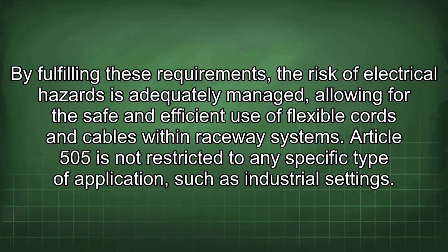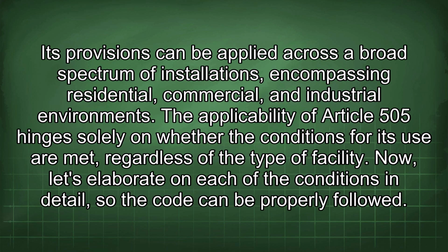Article 505 is not restricted to any specific type of application, such as industrial settings. Its provisions can be applied across a broad spectrum of installations, encompassing residential, commercial, and industrial environments. The applicability of Article 505 hinges solely on whether the conditions for its use are met, regardless of the type of facility. Now let's elaborate on each of the conditions in detail, so the code can be properly followed.